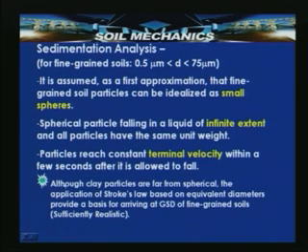Although the clay particles are far from spherical, the sedimentation analysis is carried out using Stokes law. Stokes law is based on equivalent diameters, which provide a basis for arriving at the grain size distribution of the fine grained soils. This is a sufficiently realistic assumption to arrive at the fine grained soil percentage.